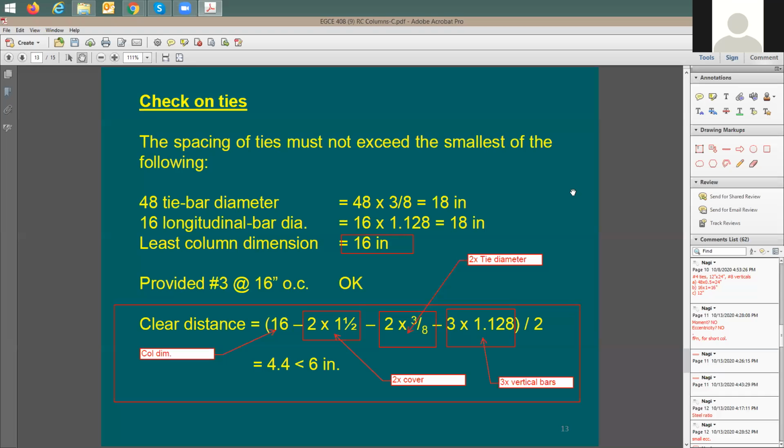I would have to say from the notes that I have here, it's to combat the eccentricity. Okay, let me repeat the question. You understand that this 6 inches is because of the seismic requirement, like for earthquake loading, right? Yes. But this column here is not supporting any earthquake loading, right? It does not. So why do I care about it? Why would I do a seismic requirement in a non-seismic member? Is it just because we're trying to provide the confinement? No.